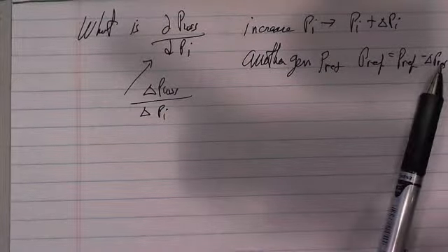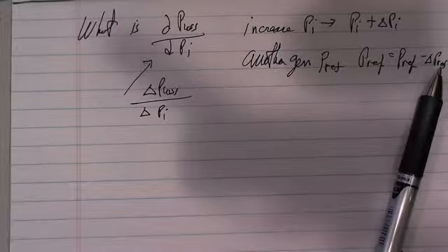The original B matrix methodology did it slightly differently. It said, okay, if I increase Pi by delta Pi, and then I let all the load go up so that the sum of the increase on all the load was exactly equal to the delta Pi, again adjusting for the loss change, then that's a different way of looking at it. And you can reconcile these two with each other. Not a big deal. The B matrix has virtually disappeared. We used to carry it in the textbook.